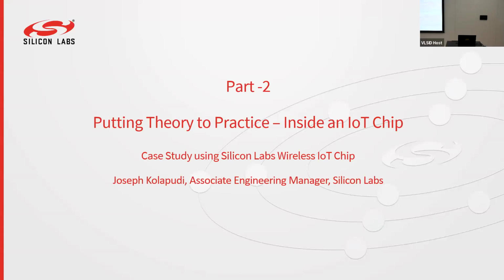It's available. You showed a slide in which there were multiple subsystems, RAMs. Which block would consume more power? Usually the wireless transmitter, because the transmitter has a power amplifier that is very inefficient, less than 20% in most wireless scenarios. So when you are transmitting, you consume the highest power. So you try to reduce the transmission time.